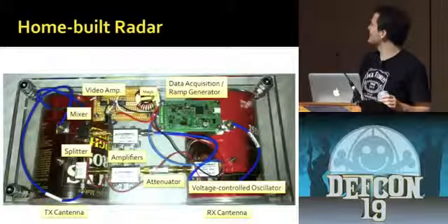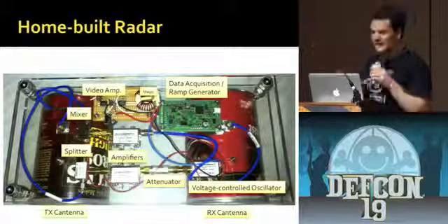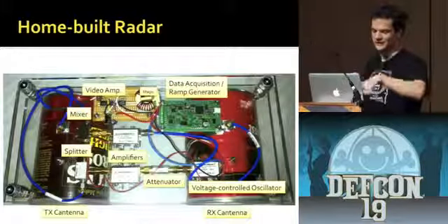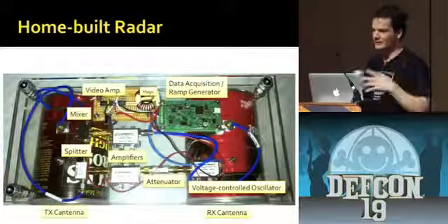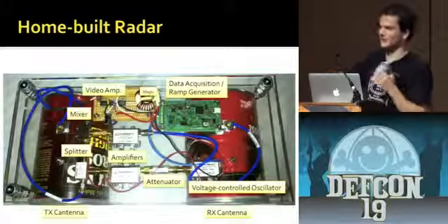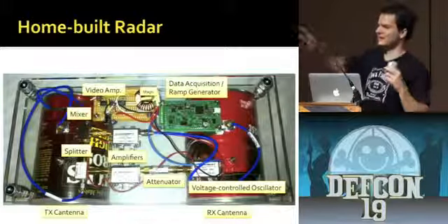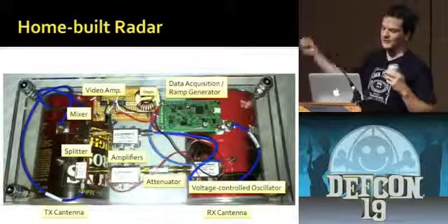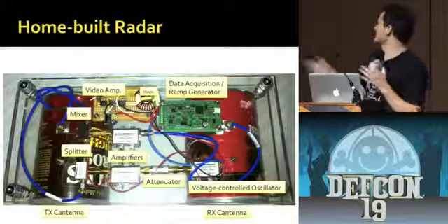Oh, so the reason that's there is because when I was trying to make this thing USB powered, I just wired it onto the power for this other stuff. Everything on here runs off of 5 volts. So I plugged the USB in, and then the computer doesn't like that. It just turns off the port. So the problem was the inrush current was too high, and I needed something to slow that down.